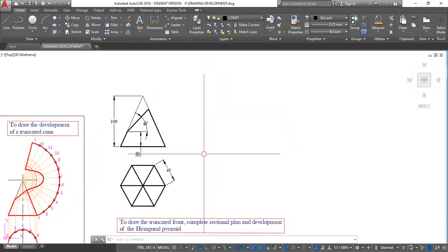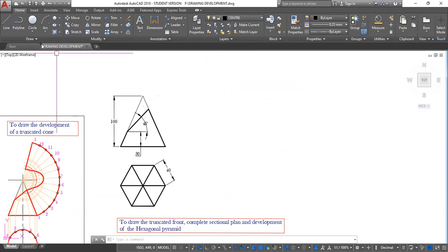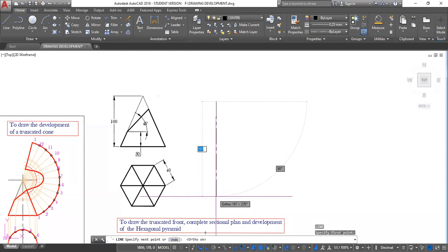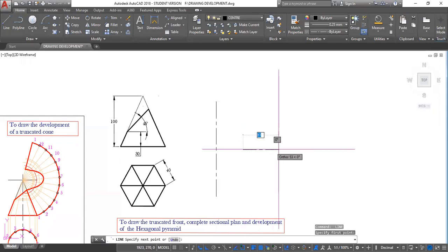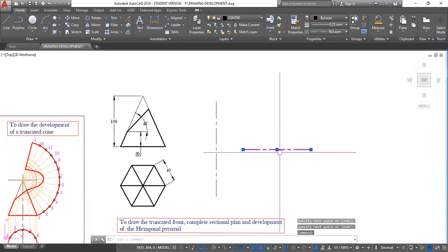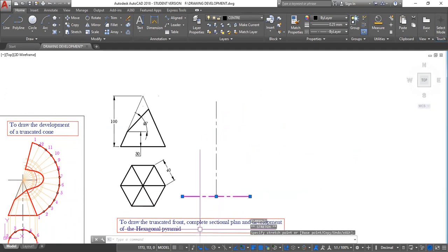All right. So the first step is to establish my center line. So I will be changing to my center layer. My center layer. I type L, enter. My starting point here. Activate orthogonal mode because I want a perfect vertical line. Escape, spacebar to reactivate line. Click here, move, enter. I click onto this, then I grab the middle and I move it to this location.